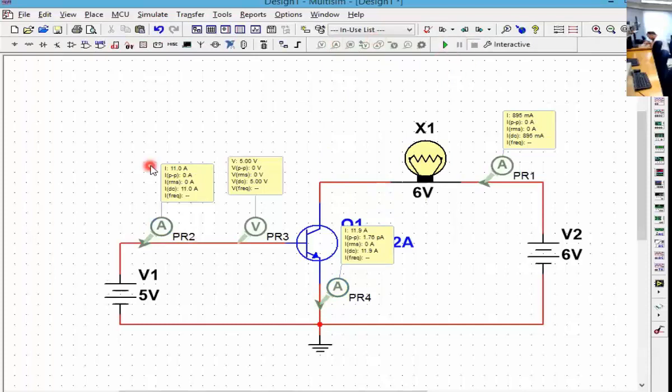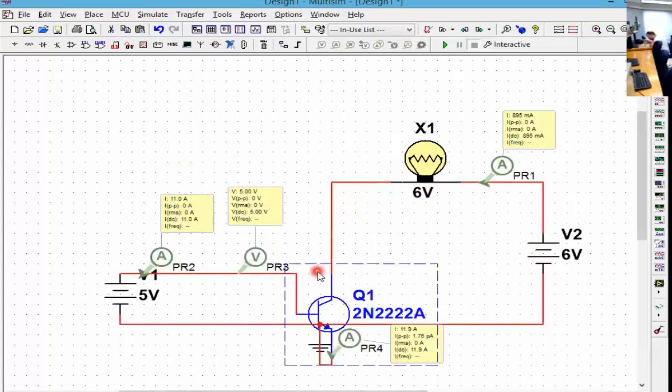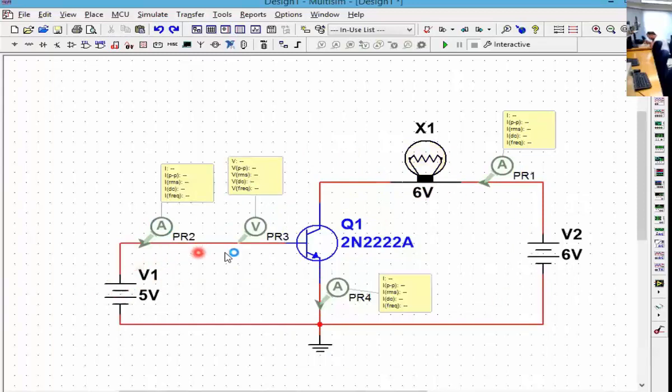Both currents together. That's exactly right, which will come in the next slides, because see, this base current is going like this, and comes back like this. So you see that on the emitter, the base current goes this way. But on the collector as well, the current comes like this, goes like this. But the collector side loop is this one. The emitter side loop is this one.